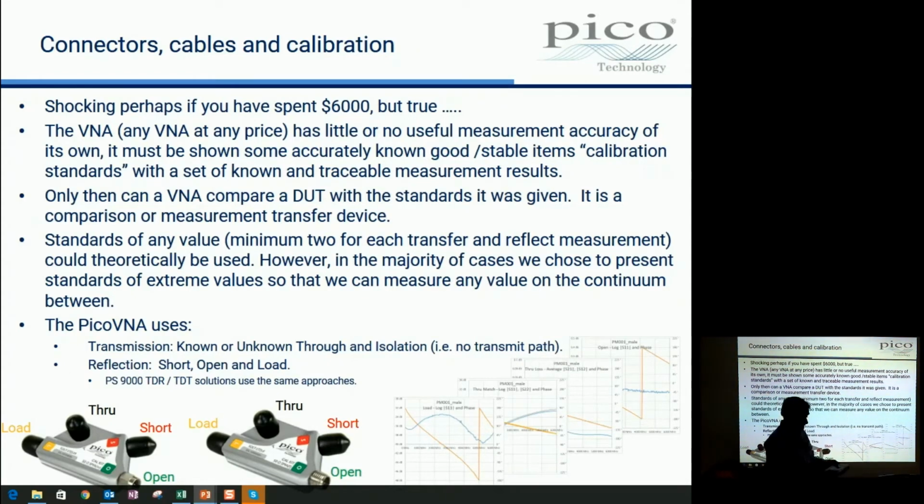So in the calibration kit, up in the top here, there's a tiny little USB stick. And that has the data for these serial numbered standards, 2 files, one for this one and one for this one. And it has 4 sets of data on it for each of the components embedded in the standard.